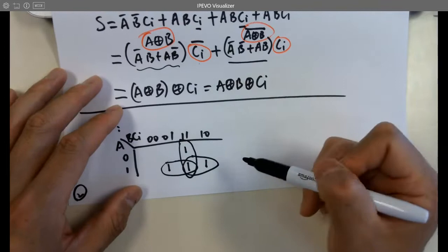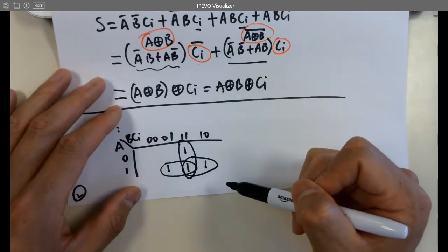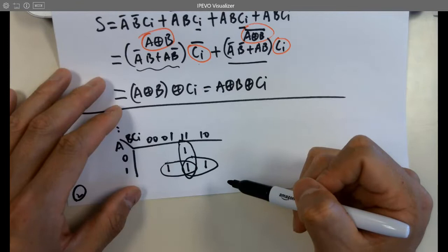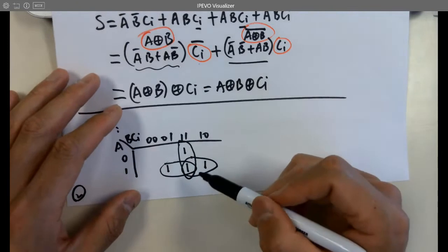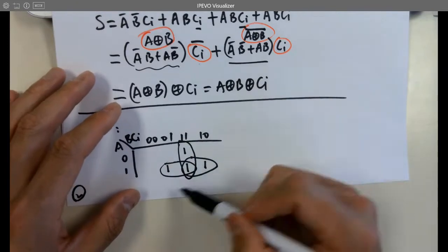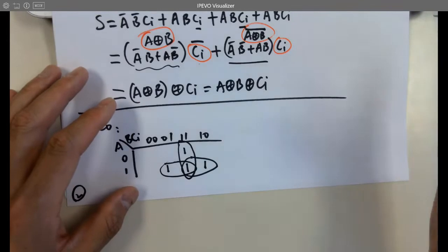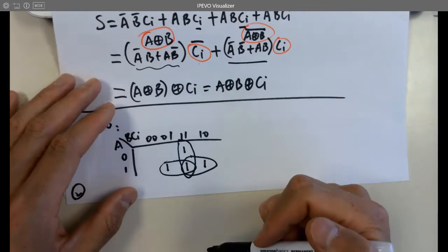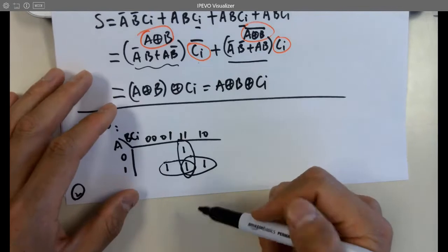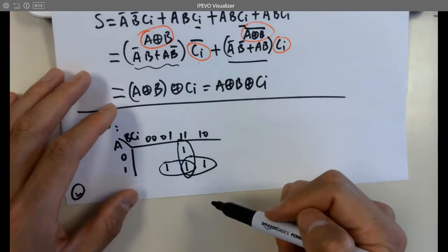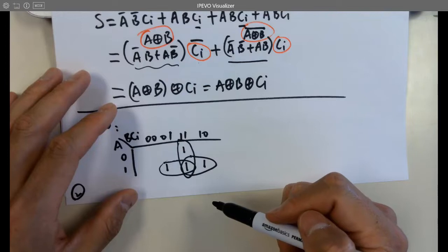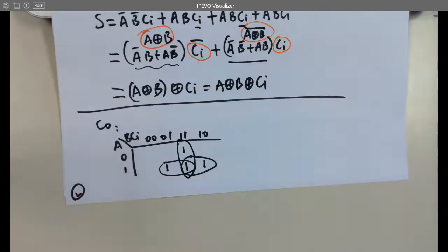That's a better way to do it, but not the only way to do it. Can you group the bottom one? No, 3 of them, they're not simplifying. You can, but it's not helping. So either 2 or 4 or 8. Why is 3 not working? Because 1 bit changes. If you have another one, the third one, then both of the digits are flipping. So you have to use that one either being grouped with one of the first 2 ones each time. You know what I mean?